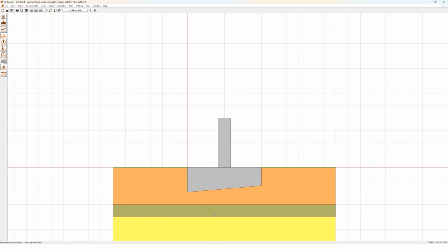And we can also add slopes and excavation stages at the surface. So we can define different stages with different abutments of the foundation. And you can also define a groundwater level, which is always associated to an excavation stage, since it can change from stage to stage. So if you want to define a groundwater without any excavation stage, we must at least define 1 excavation stage at the top surface.